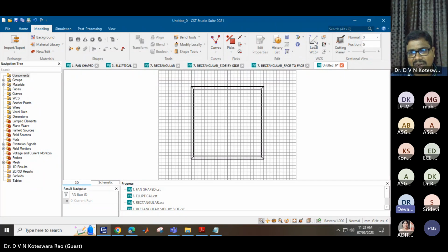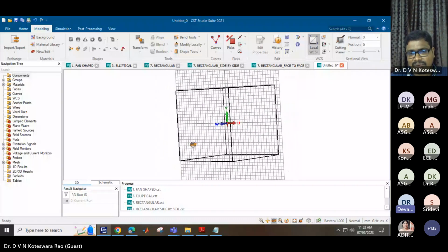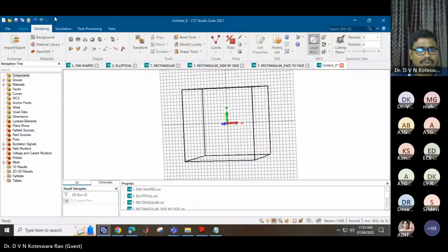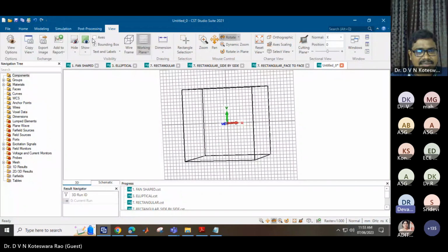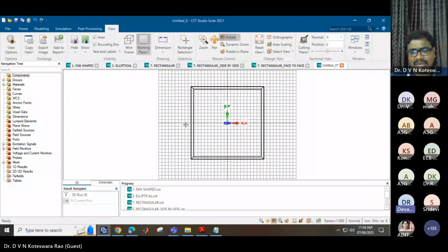And there you have the local working coordinate system, local WCS. The local working coordinate system consists of UVW components, whereas the axes coincide with UVW or coincide with XYZ respectively. So XYZ are global coordinates and UVW are local coordinates.